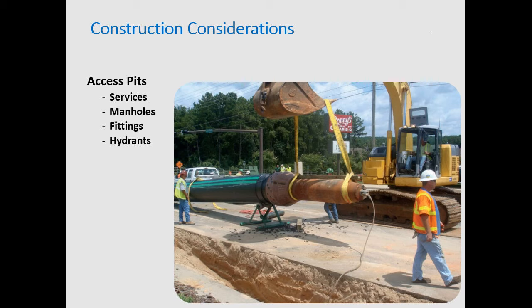On the sewer side, you're going to be excavating at the manhole, dropping it in. You're trying to minimize that. If there's equipment, that's where the pneumatic is advantageous, where you can drop in the winch and pull to that manhole. And then once the hammer's there, you can take it out and not have to excavate. You don't have to excavate at one pit. You don't have to excavate at both ends.